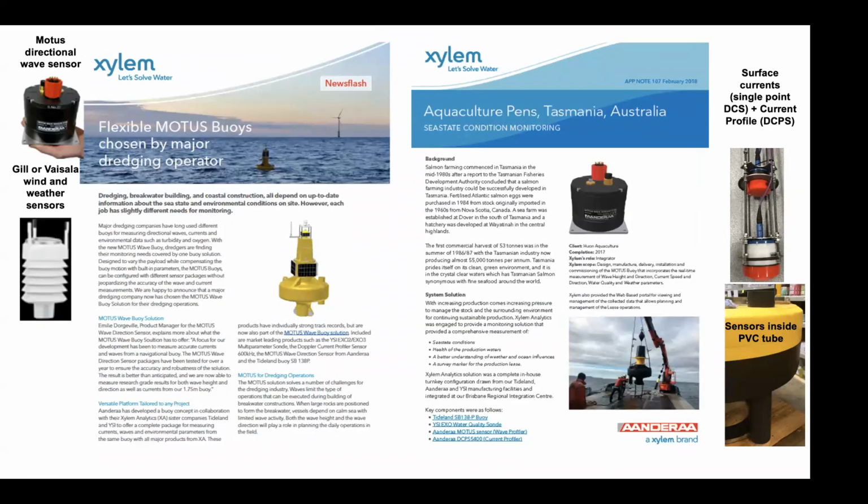We have also delivered many of these buoys for other applications which are not navigational purposes, and here are two examples. Still they use the same type of buoys, but normally then they add water quality, and then typically we integrate the YSI EXO sondes. YSI is a sister company of ours to Aanderaa, the same group Xylem, and the advantage here with the water quality sensors is that they have anti-fouling built in with the wiper and copper nickel guard. So these buoys are used by major dredging companies, Dutch and Belgian, and then also several of these are used in aquaculture. This is an example from Tasmania for salmon aquaculture.